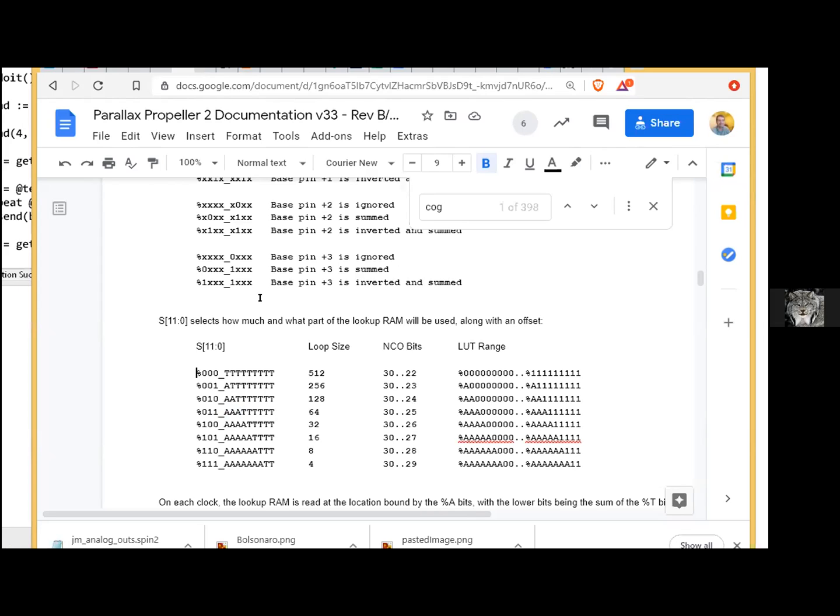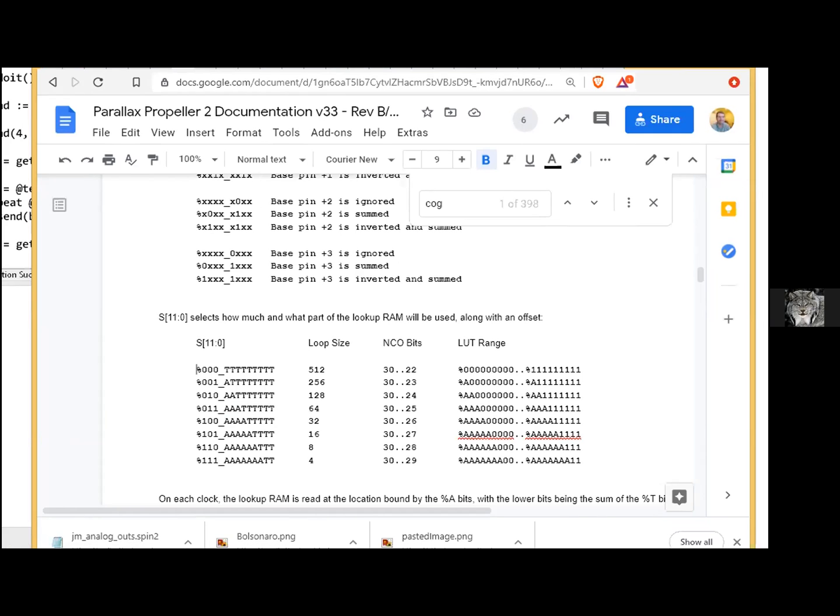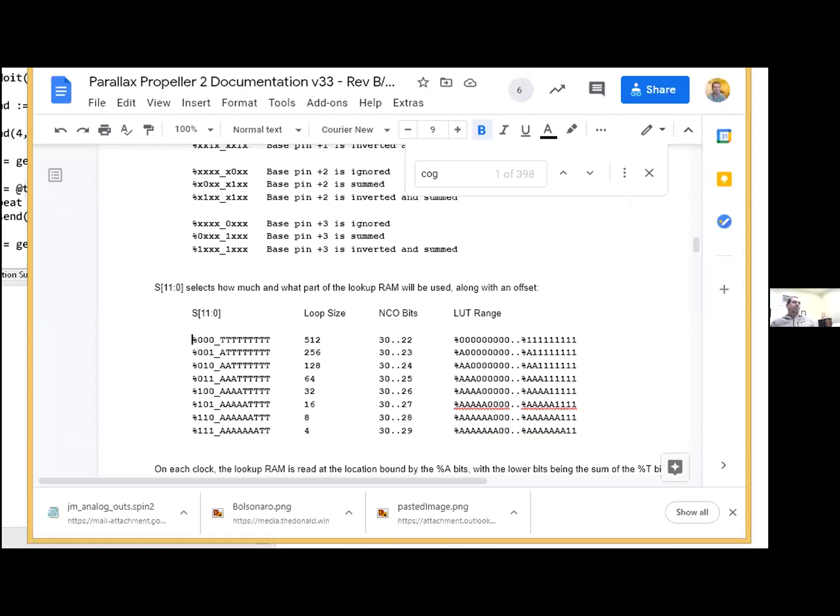You've basically made a hardware stream tracker that can play samples at super high frequency. Yeah, it'll output each sample at the clock, 1 per clock. You can configure the streamer to go at less than 1 per clock rates though, right? Oh yeah, that's what that 32-bit NCO value is for. So you can slow it way down to audio frequencies if you wanted to, or you can run it super high. Absolutely, you can go from synthesized radio, video, down to audio and below. You have 32 bits of frequency control, so you can go down to fractions of a hertz.